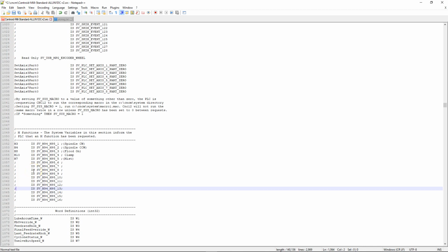But yeah, with that, the ones that you probably don't want to change are the M3, M4, M8, and M7. These 4, you want to leave as is because the software is actually hard-coded in there to set those particular bits. I actually do know of a customer that once tried to make things simplified, sort of like what I just did, and they issued the M3 and they tied it to the 3rd bit in that system variable macro to coincide with the macro callout.